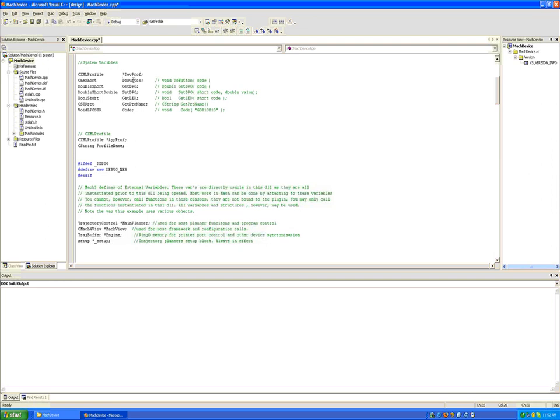You can also see that I've instantiated about 6 routines, do button, and you can see in the comments I've given you an example of how to use it. You can use these at any time in your DLL, and those familiar with Mach3 script will recognize them. It's do button code, double get DRO code, void set DRO, get LED. C-string get pro name is not something that you will need to use. This is used in conjunction with the CXML profile. And then there is code for sending G-code straight to the program.